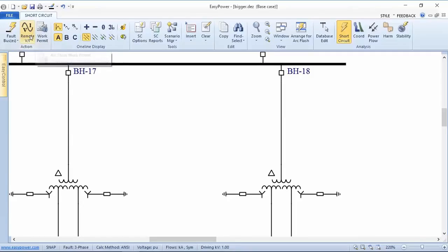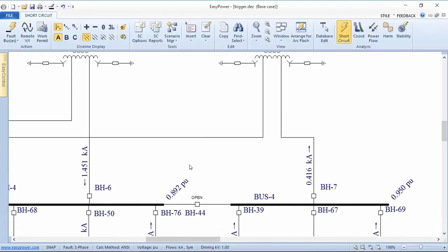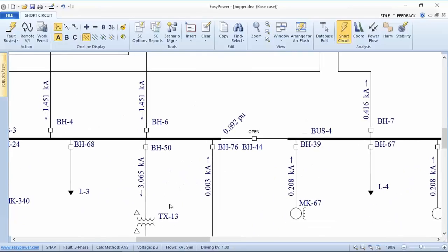and if we don't select a single bus and do all of them, we'll see that the contribution goes up through the main bus through two transformers. This will end up being significant when we look at the remote protective devices, because we'll have contributions to a fault that sometimes we don't expect, and it's because there is an impact on remote buses in both voltage and current.